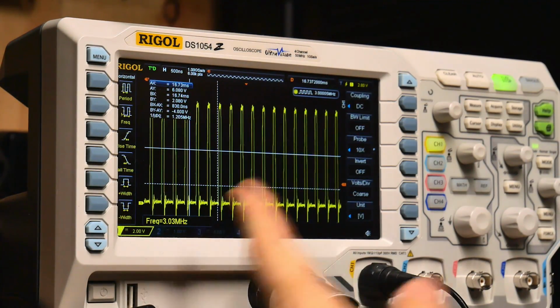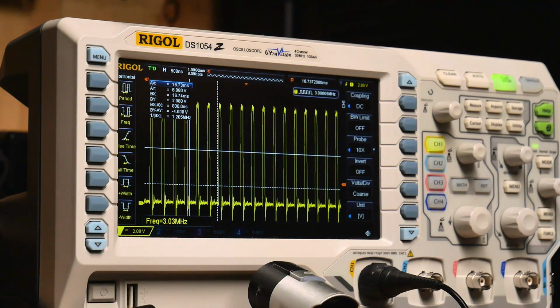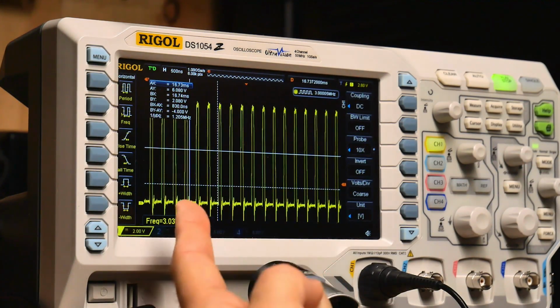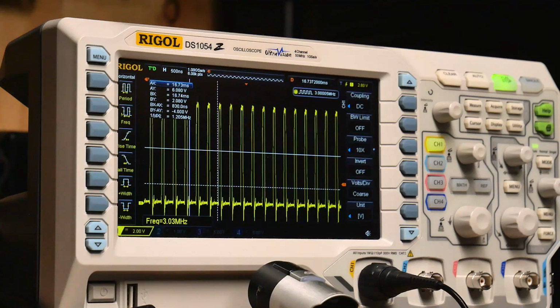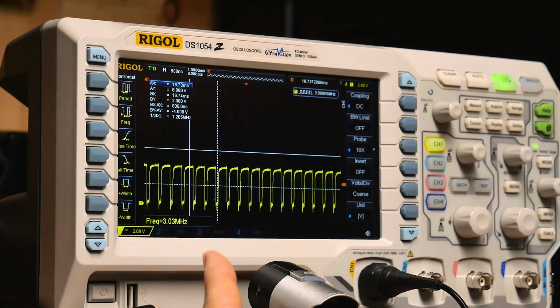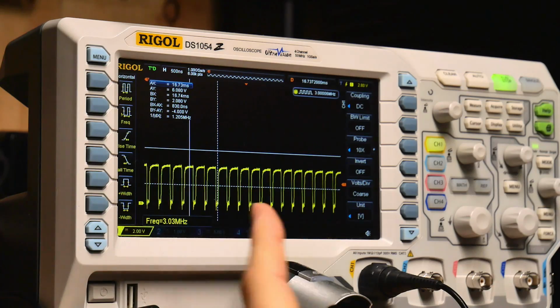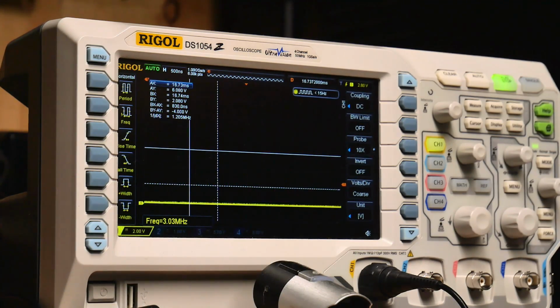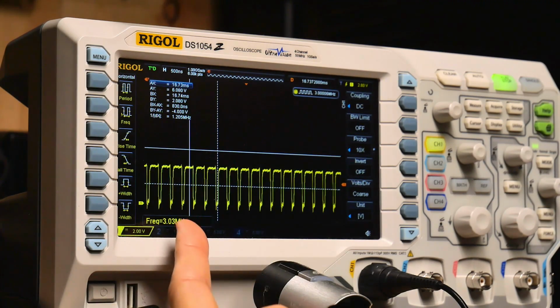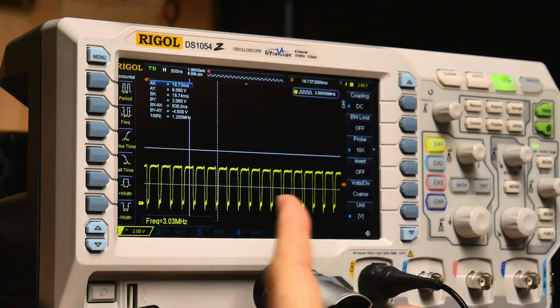This is the next pin. Also looks good. 3 megahertz, 12 volts. That looks great as well. No problems there with that one. That's the last of the 12-volt clocks. And we have a 5-volt clock, the third one, and it's looking good. See, it's going down. It's kind of active low, I guess it's called. And that's the 4th and final 5-volt clock, and that also looks perfect.